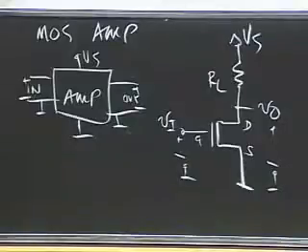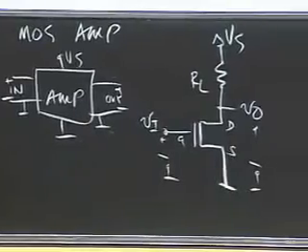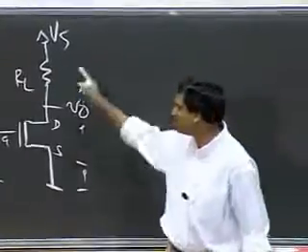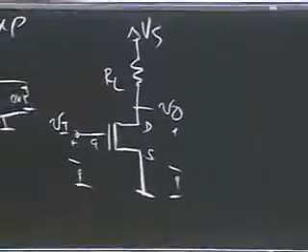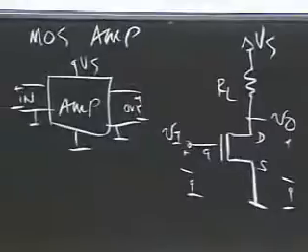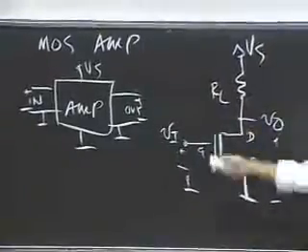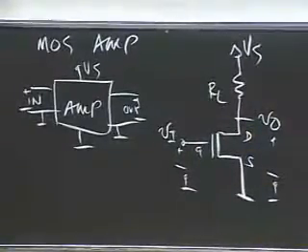It turns out this is not surprising. You've seen this before. This was our primitive inverter circuit. So what's different here? We showed you the circuit as an inverter. What's different here is that when we look at MOSFET behavior as a current source, this behaves like an amplifier.